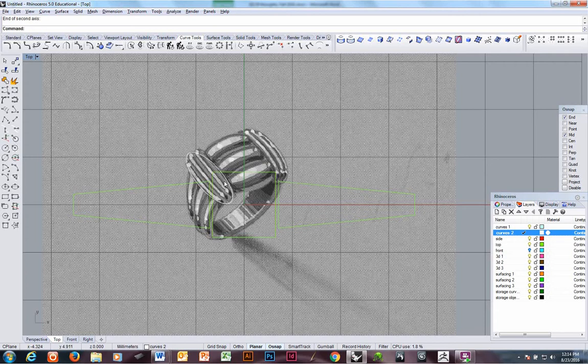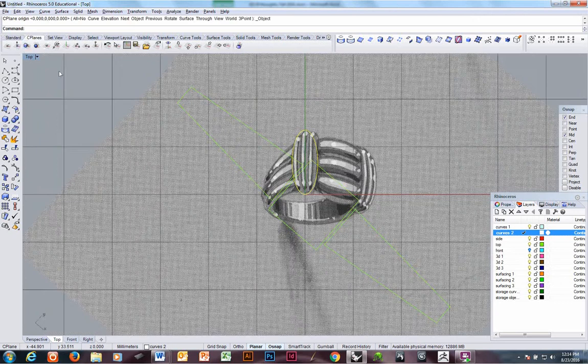What I really wanted to do is just kind of line up in the direction. Remember from our cplanes from last semester that if I line up an ellipse, I can then set the cplane and it'll keep the same direction. Cplane to object. There we go. Okay, so now the cplane has lined up to follow along with this for me.